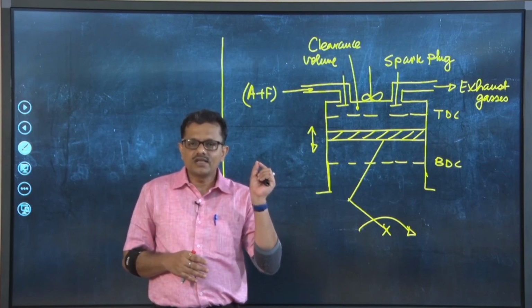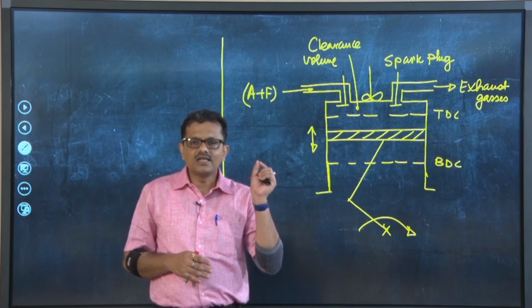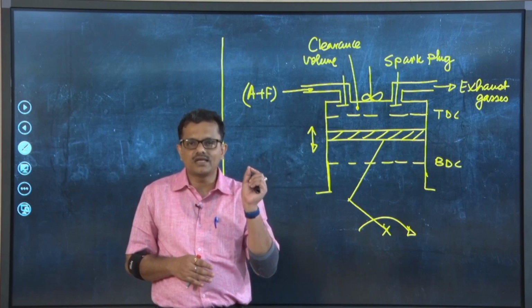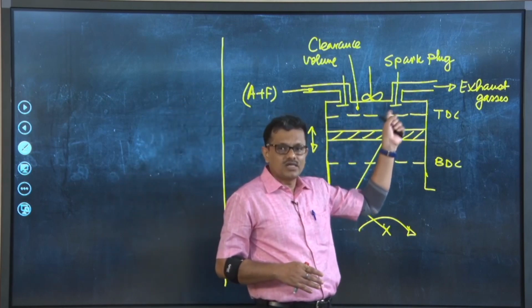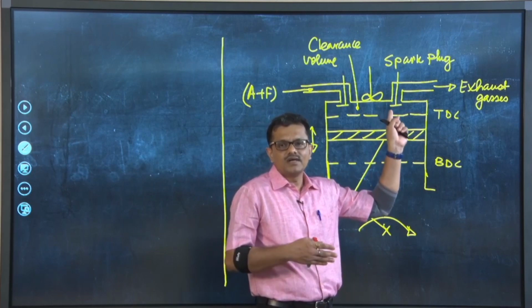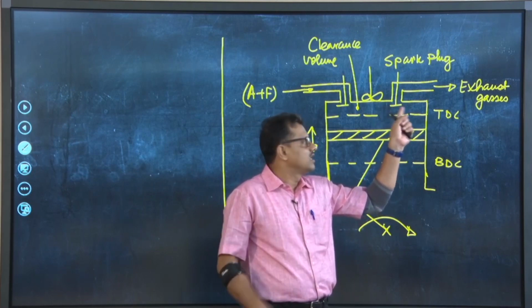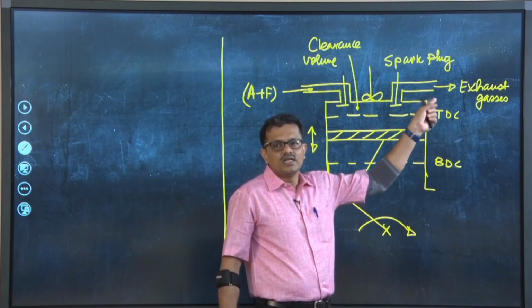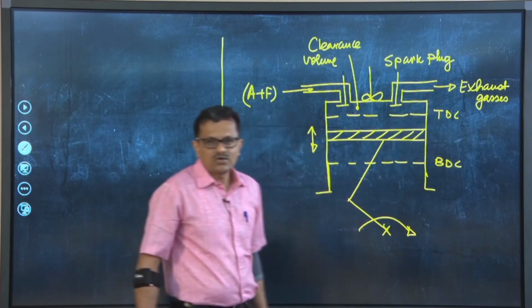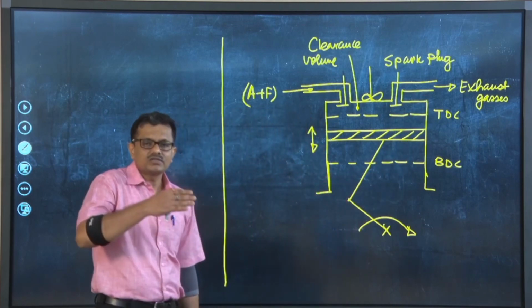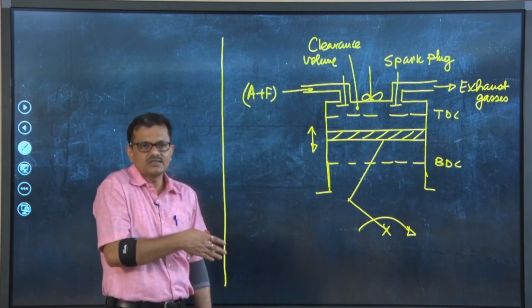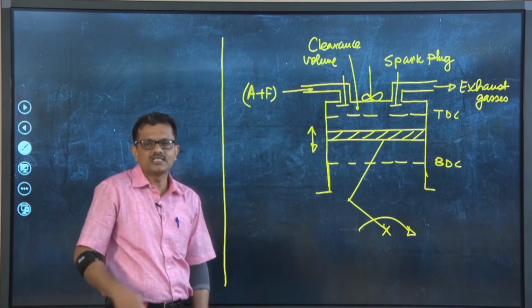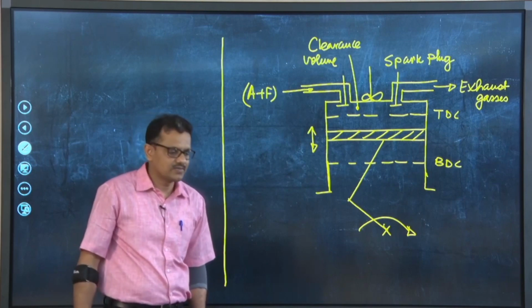We have understood the cycle, and this is not a true thermodynamic cycle, because at the end of the cycle all the working substance, which is nothing but several gases, will leave out from the engine cylinder. So, those gases are not cycled back into the process. So, it is an open cycle. So, it is better to say a mechanical cycle.